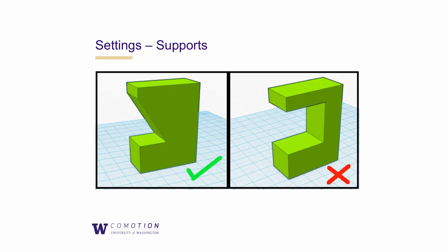So if you take a look here, which of these files do you think comes out best? The upside down with the support material. Why is that? Because it has more surface contact. Exactly. So that's a consideration of your 3D printing, and a lot of it is based on experience. If you're really smart, it might be really intuitive. But for me, it took quite a while to figure out that laying it down flat, where the most surface touches the level bed, is the best print.